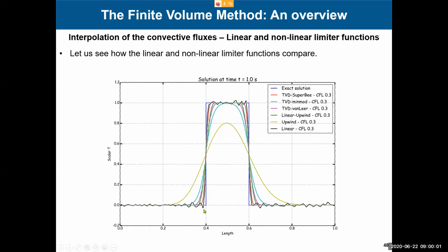So it might happen in my case. Usually, most of the time I work with aerodynamics, so sometimes I don't care about this. But in your case, if you are working, for instance, with chemical reaction or combustion, this is unacceptable because you might be triggering an artificial reaction just because you have this numerical oscillation.